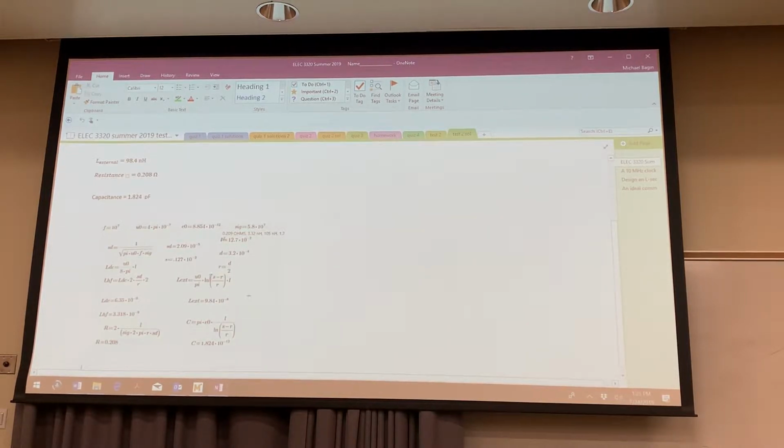Next is the external. Well, the external inductance, you can go by calculating the B field, then integrate the B field over the area between the two, right? And then once you do, that's the flux, and divide the flux by the actual current. Now remember, the flux caused by one wire integrated over that is the same thing as the flux caused by the other wire integrated over that, due to arguments of symmetry. And what it comes down to, you got to remember this though, your range goes from the radius of the wire to, and then it's going to be the actual separation distance minus A.